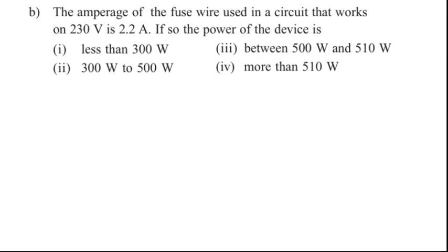So power will be VI equal to 230 into 2.2 watts. Again, this can be written as 23 into 22. This will be equal to 506 watts.